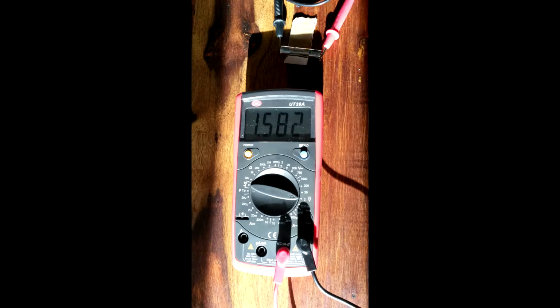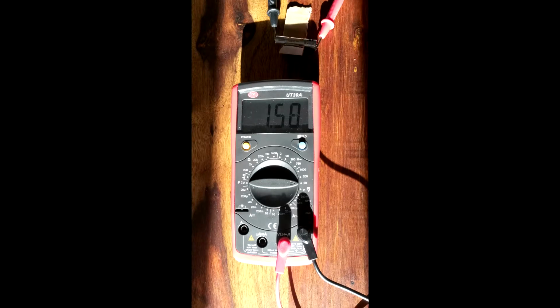So here in this picture we have a multimeter currently set at 2 volts, so the range is 2 volts or lower. Now I'm using an alkaline battery that is rated for 1.5 volts, so this meter is just reading the total voltage, which is 1.582. And in this next picture we have the multimeter set at 20 volt range. So again, same battery reading 1.58. The difference between this one and the previous one is that it gives us less decimal placement.